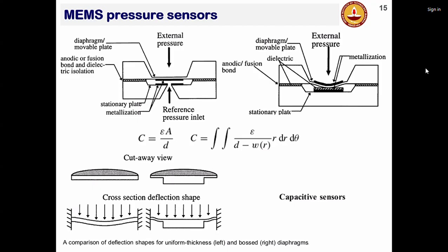So it is basically both an additive and subtractive manufacturing process. You add material and selectively subtract material through etching. So you deposit material, you etch material selectively, and you pattern them using various ways. One of the ways is called photolithography. That means you use light to actually define patterns and create this kind of structures.